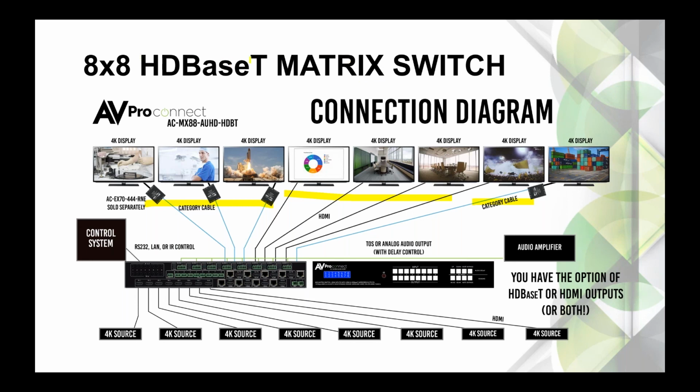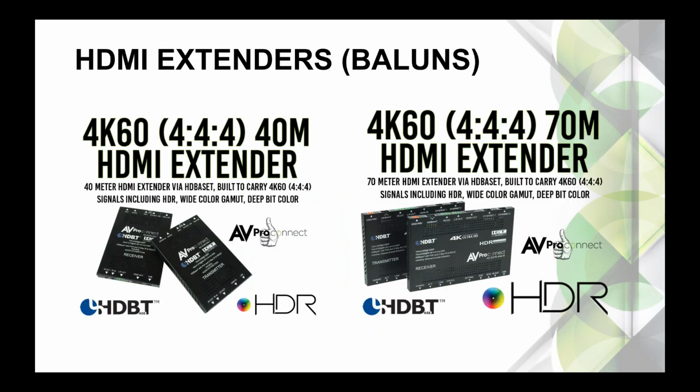So the 2 versions of HDMI extenders, and again, these are full 4K 60 444, 40 meter, 70 meter, all shipping, all available. Another thing I can point out that I didn't mention before, you can power either end. So you could, in a pinch, put an extra set of these in the middle and not require any power. And you could actually double the length of the extension, powering it from a transmit side and a receive side to two boxes in the middle.